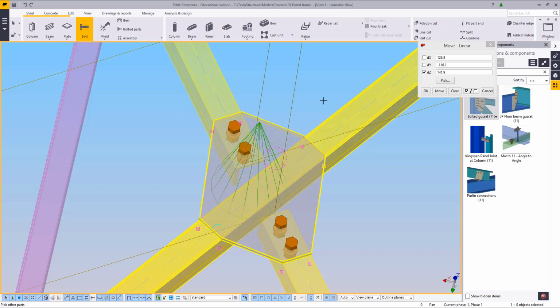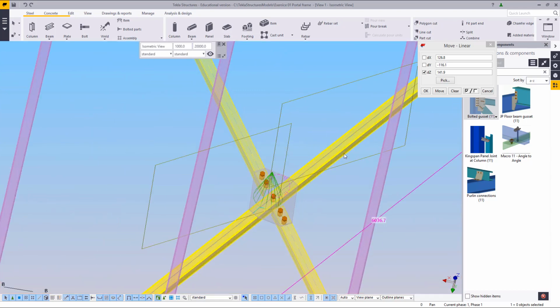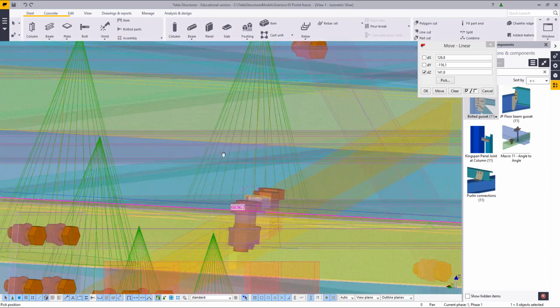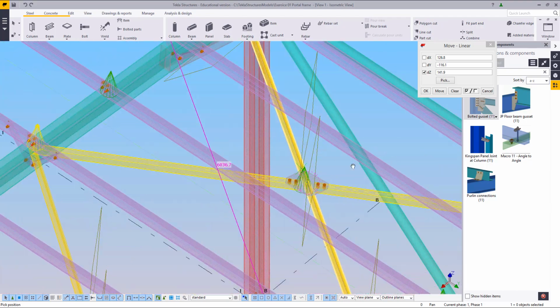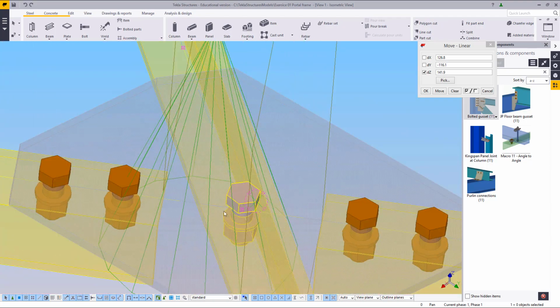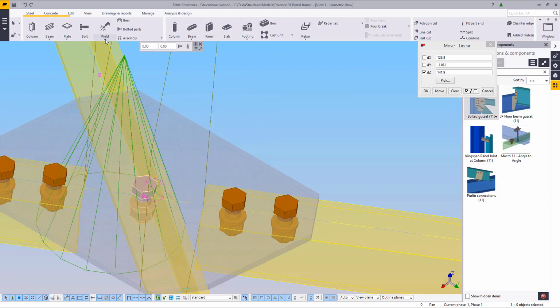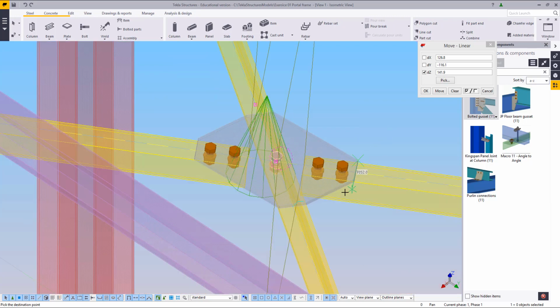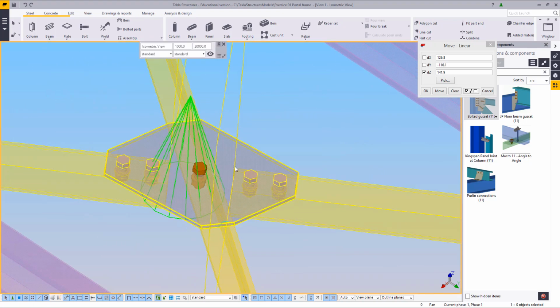What we tend to do is just put an extra hole in both the plate as well as in the angle line member, and this allows us to more easily find the correct position. We'll just put the plate on, drop the bolt through, weld the plate in place, and whether the bolt stays there afterwards or not really doesn't matter, as it has already served its purpose by that point. Copy this over.